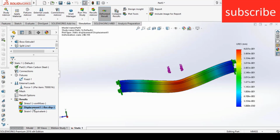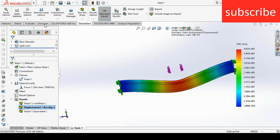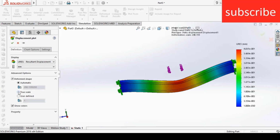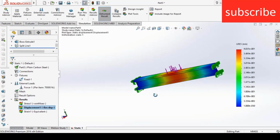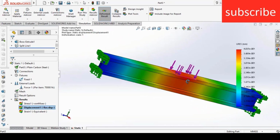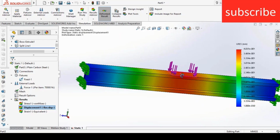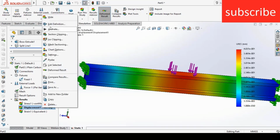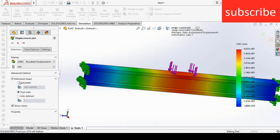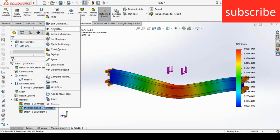So how to see the real deflection? To do that, right click on it, click on edit definition, select true scale, click OK. As you can see, this is the true scale, this is the true deflection, but from your eye's point of view it looks like a straight beam. So right click on it, click on edit definition, click automatic, click OK. Now right click on it, click on animate.